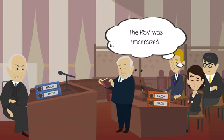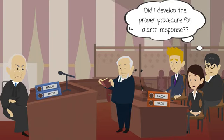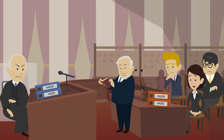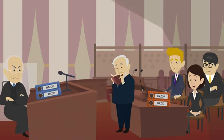I knew the PSV was undersized, but why didn't the pressure shutdown come in? Was it not independent of the failure? Did I develop the proper procedure for the alarm response? Did I consider the failure rate of the valve? There were some concerns about the control valve failure. However, it was deemed that the likelihood was low. The design was signed off by me and the management team.